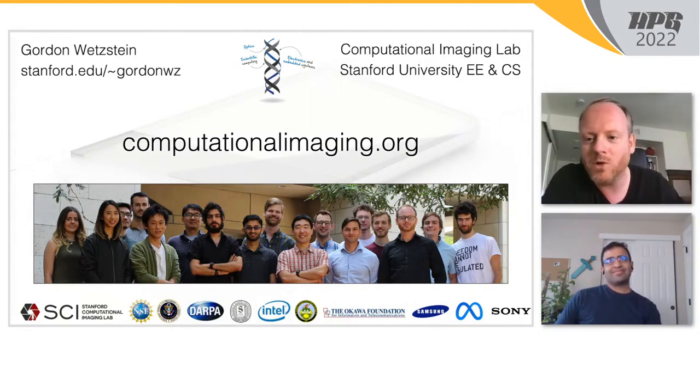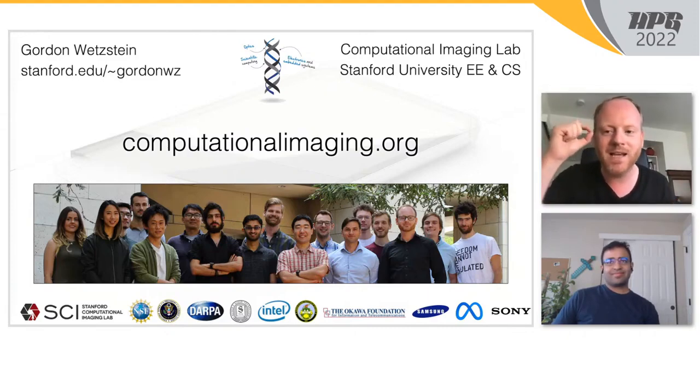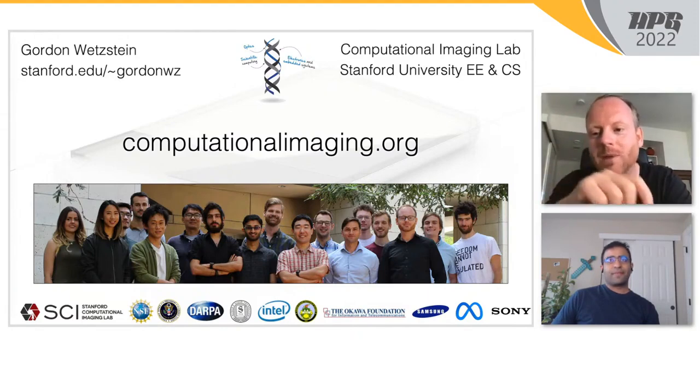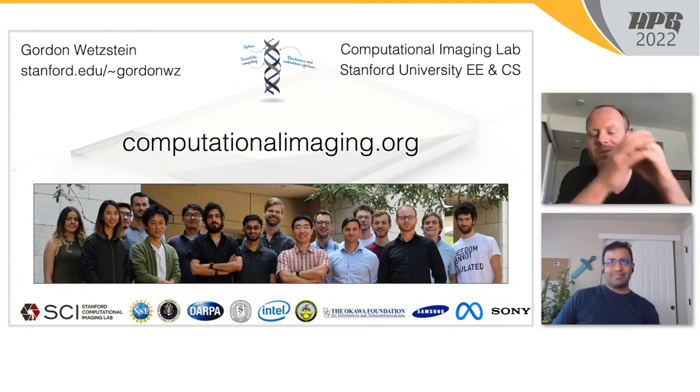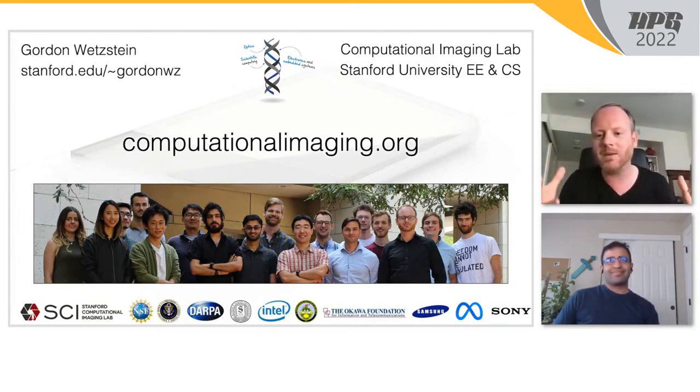For example, Compound Photonics has publicly talked for a couple of years about their smart backplanes. What that means is that you can directly dial the eye tracking location, for example the gaze position, into the backplane, and you have not just a foveated rendering mechanism, but a foveated backplane if you want. So you can directly turn on the backplane at a high resolution, but you have to synchronize it with the GPU. So everything has to be done in harmony.